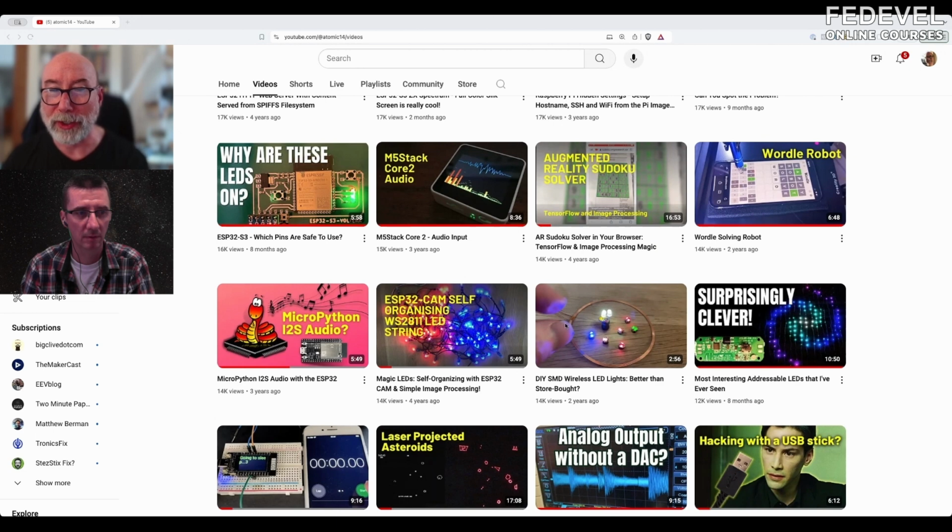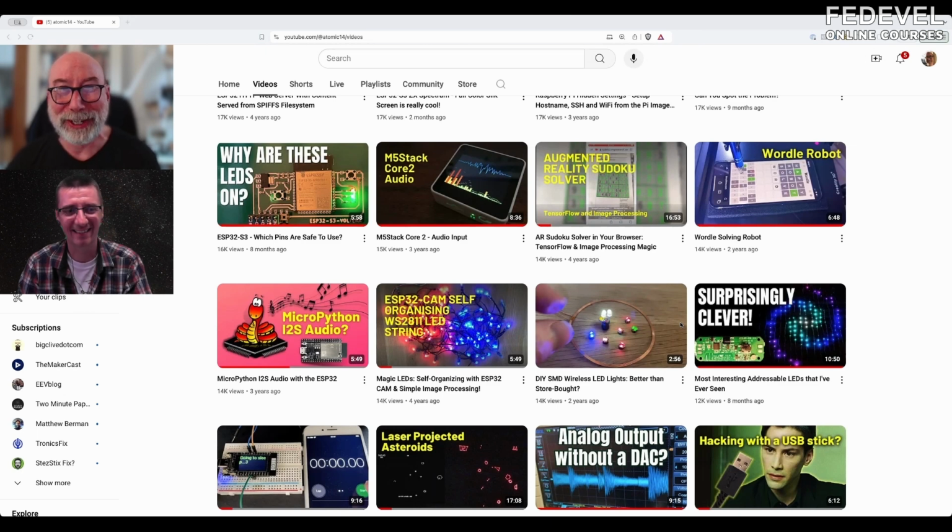But you can just use a MOSFET to drive a square wave through a coil, and it will light up the LEDs. Obviously, even with the ones you buy on AliExpress, you are pumping out a lot of interference with these things. So if the FCC or anyone like that comes knocking on your door, then probably turn it off quite quickly. But it probably is quite short range, so you're probably okay. But it's not certified in any way anywhere. Until your chocolate is melting, like how the microwave was discovered, you feel like your desk is getting warm.